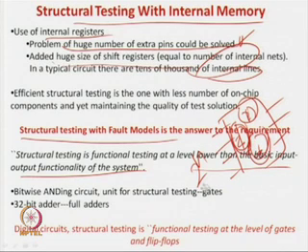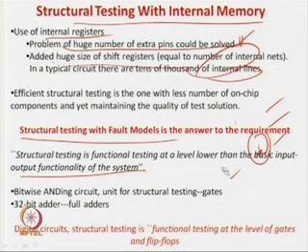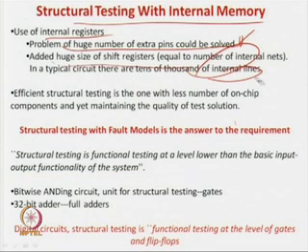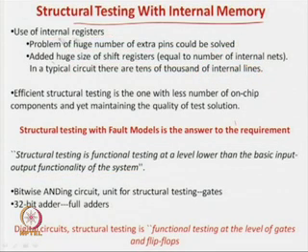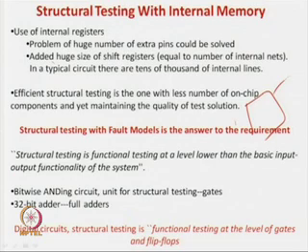In general structural testing, the term we use in testing, the basic block levels are the gates, and sometimes we can go a bit higher. Like in the previous example, our unit was a full adder. We were not bothered to go inside the adder and test it, but rather we were finding out that structurally the interconnection should be fine.